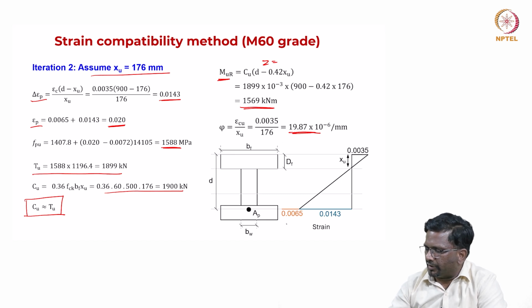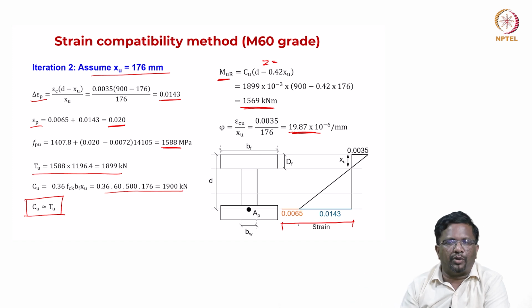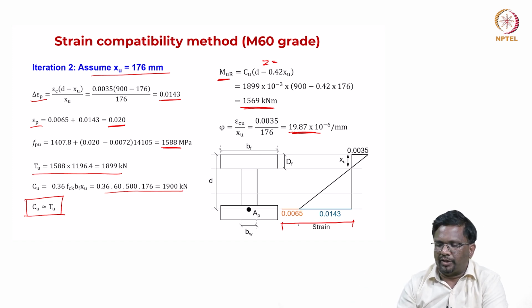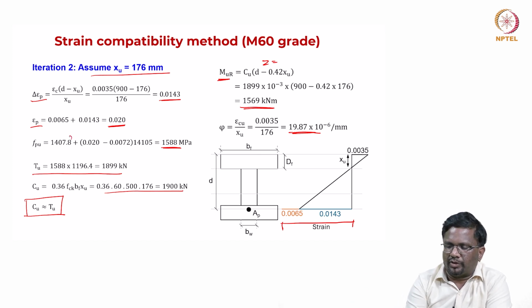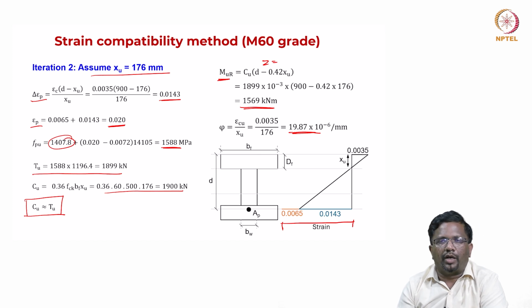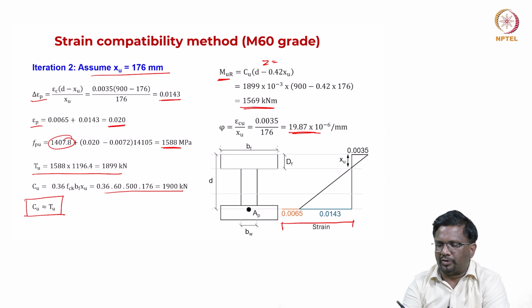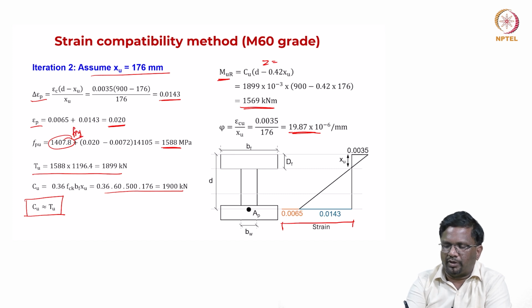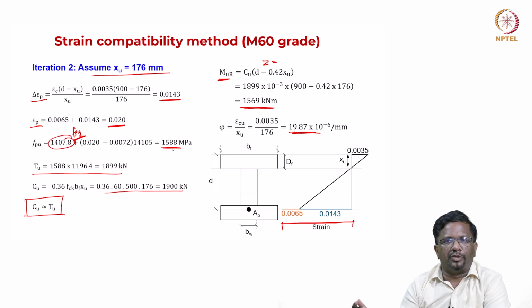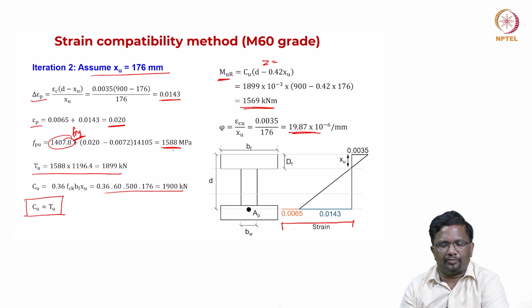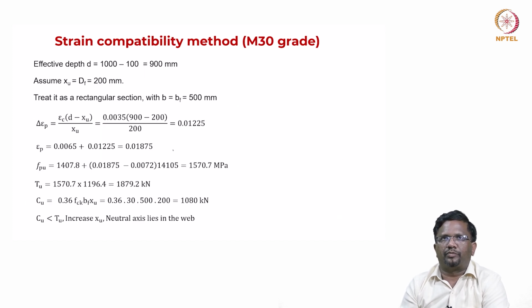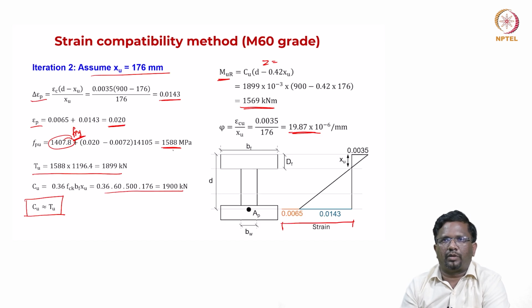So, you see here this is the strain. So, it is really stretched, okay. It has gone beyond its yield, right. So, the yield strain as per this was only this, right. So, this is an under reinforced section, right. So, this was your FPY, right, and so we have gone much beyond that. So, that means the steel has actually yielded as per the curve, right.